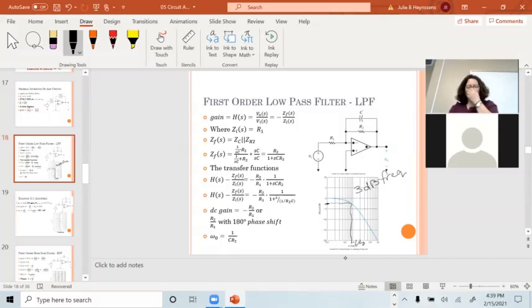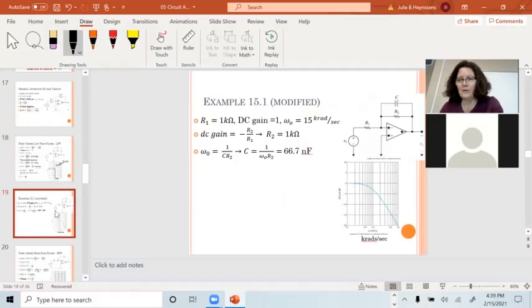This is the most common response that you will see out in the real world, these low pass filters, not some of the stuff that I gave you to stretch your Bode plot brain so you don't freak out when you see what the transistor frequency response curves look like in 380. They're really messy, but we put a pole in there so that we don't care about the messy part. And then they look like low pass filters again.